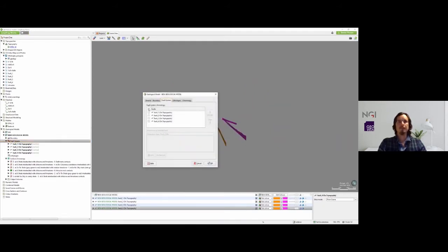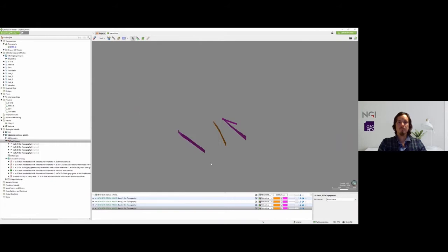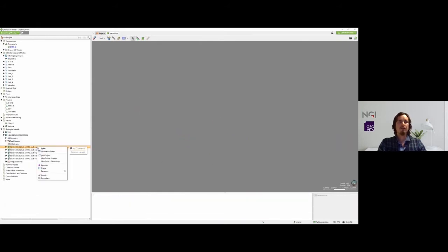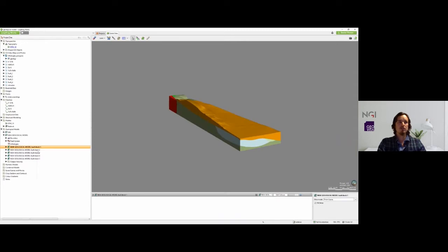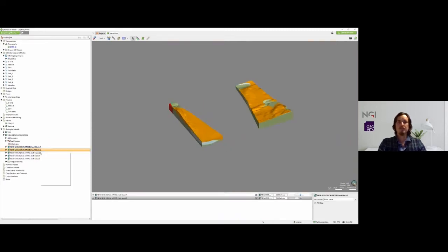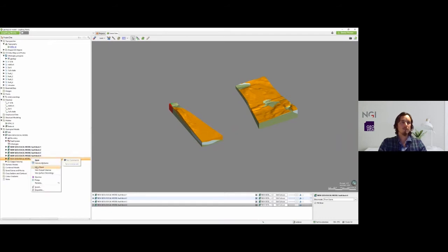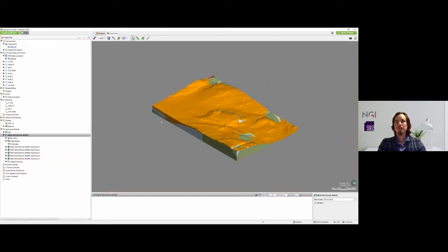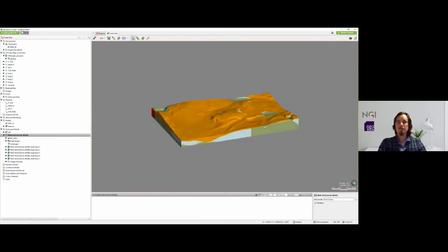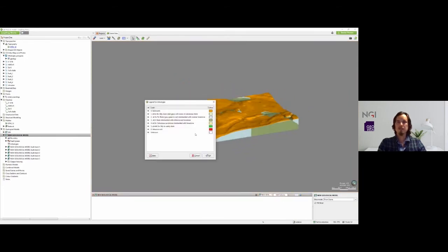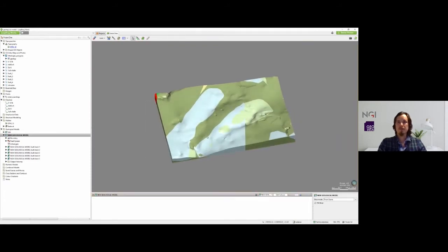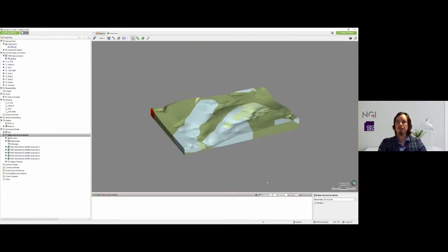And then we gotta activate the faults. And now the model is created into each fault block. And we can view these blocks by dragging them to the scene. Okay, so now we have the complete model. We can turn off the sediments to look at the lithologies. That's good. That looks pretty good for a quick model.